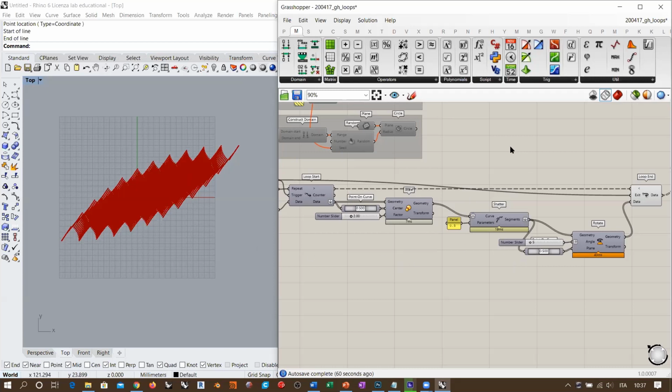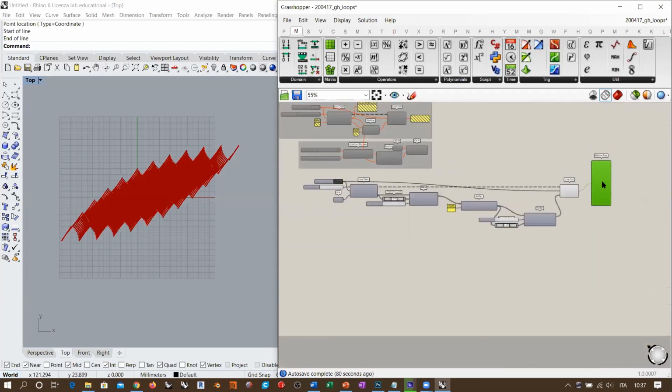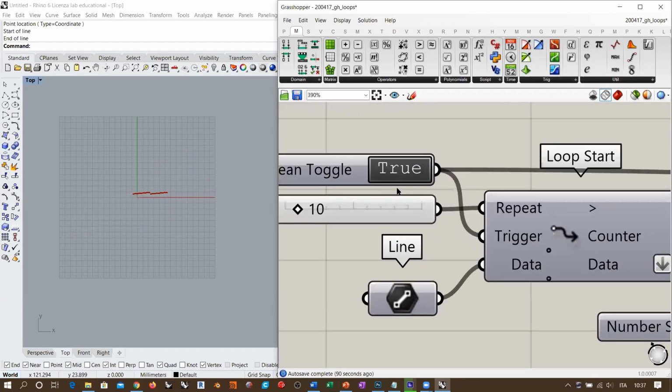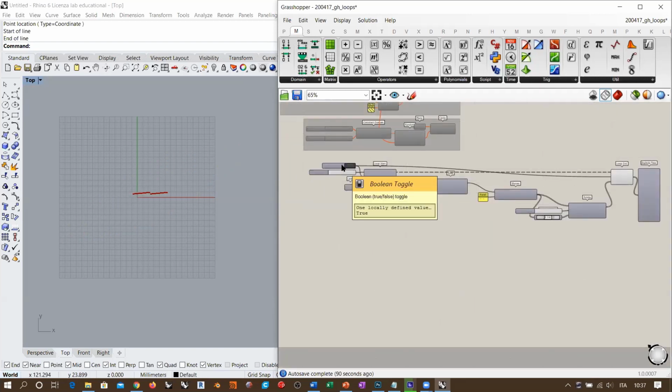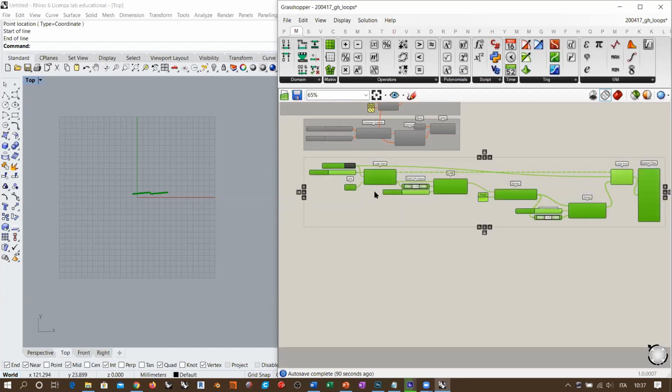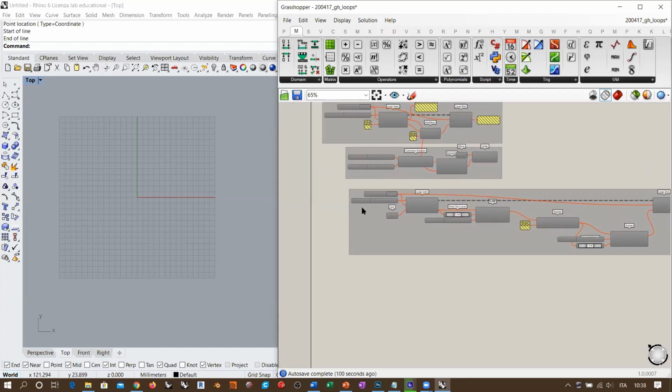Also, if you're not into coding, line coding, then you can create loops like this in Grasshopper using some plugins like this one. Also, you can create conditional statements like selecting different data streams and so on. But it's just knowing what sequence of functions you have to use. In this case, this is basically what I wanted to show you with a geometrical operation. I'm going to trigger the loop, and I'm going to group and turn off everything here.